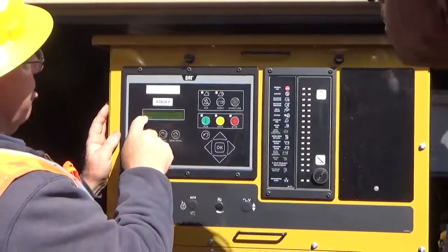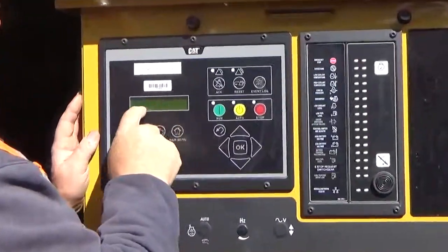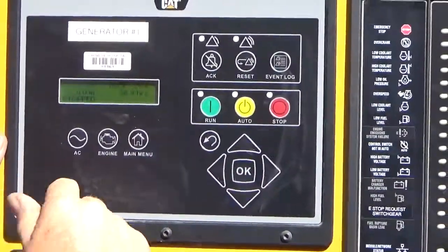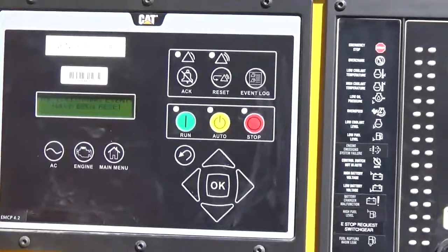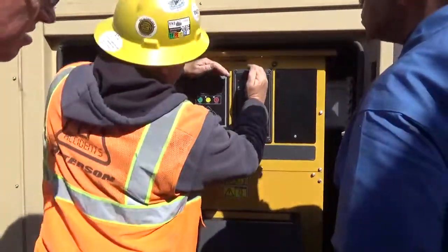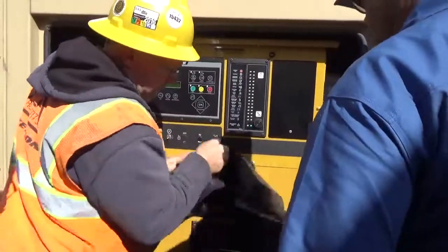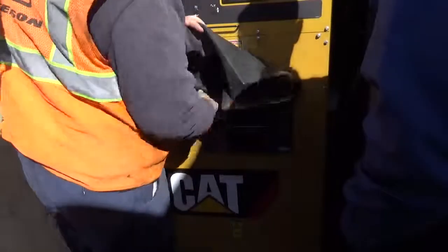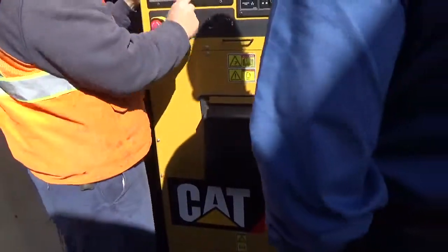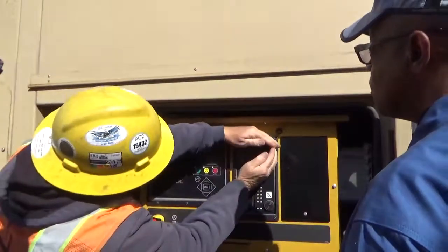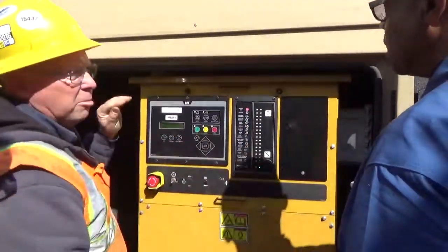It says reset all events, or hit cancel. So we're going to hit OK. Now it has removed it. You heard it click, so it cleared the shunt trip coil. So we're in stop, and the lights are both out. Now you can reset your breaker. And you go back to auto, and move back to a clear board again.